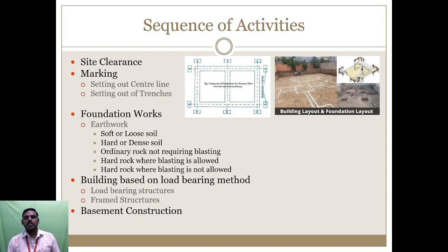Not allowed means there are a lot of constructions nearby, and their foundations could also be damaged when we go for blasting. So in this type of condition we have to construct on top of the rock up to the required depth of foundation.